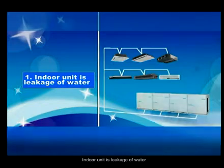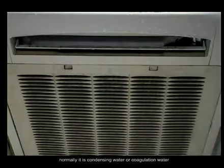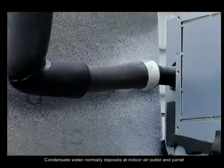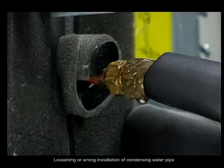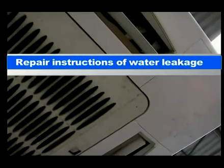Indoor unit is leaking water. Check where the water leakage is from, normally whether it is condensing water or coagulation water. Condensate water normally deposits at the indoor air outlet and panel. Condensing water is normally caused by a malfunction of the drainage pump, or a loosened or wrongly installed condensing water pipe. Repair instructions for water leakage.